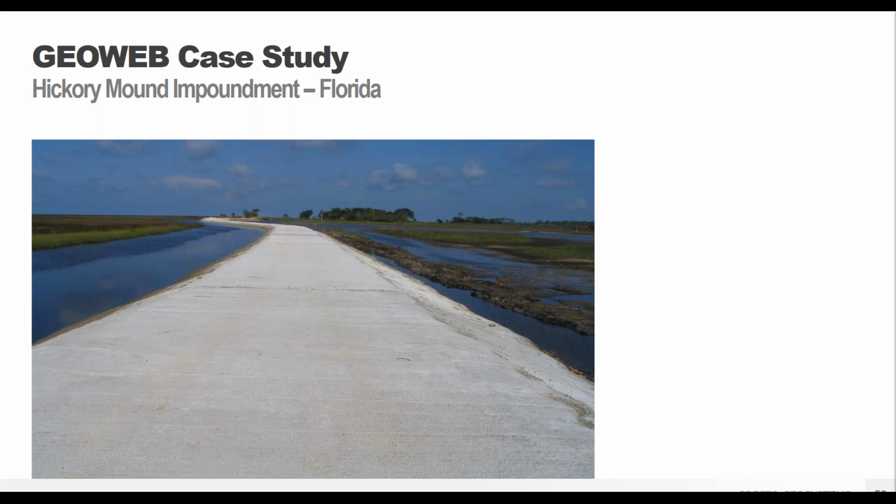And so they were able to pour the concrete, you screed it flush to the top, make a nice smooth surface, and then let it pour down on the sides. And now you have a good, in place maintenance access road. You're not going to have to come back and keep rebuilding that earthen dike every time you drive on it. It's going to be able to support heavier vehicle loads because you do have that good concrete surface now. So just an interesting little application building through this sort of impoundment area.